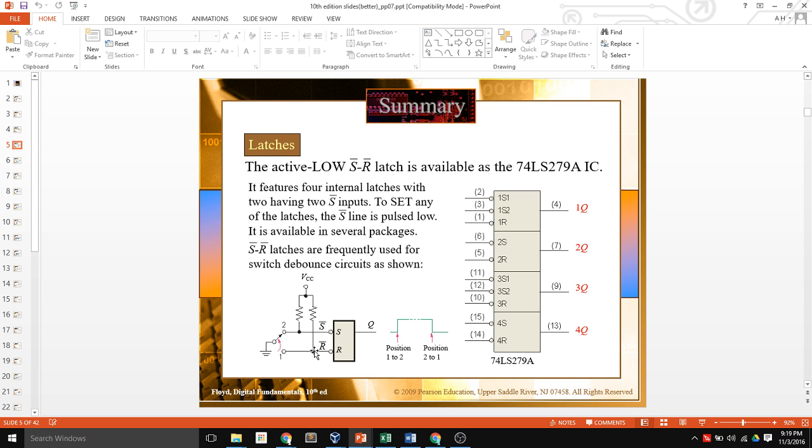And so what's happening here is these resistors are called pull-up resistors, and it's putting 5 volts or a digital 1 on the inputs at all times. And then this switch connects one of the 2 inputs to ground. Only one of them can be connected to ground. And so you flip the switch, it will go from set getting a 0 to reset getting a 0.